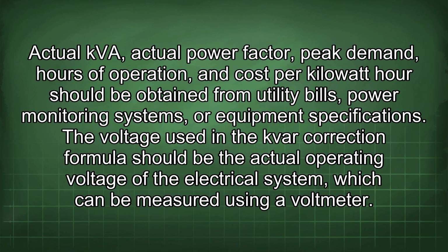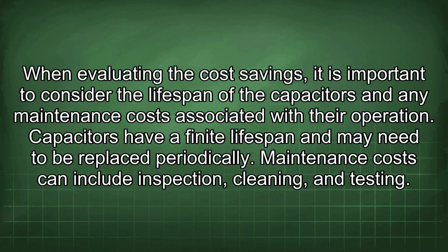The voltage used in the kvar correction formula should be the actual operating voltage of the electrical system, which can be measured using a voltmeter. When evaluating the cost savings, it is important to consider the lifespan of the capacitors and any maintenance costs associated with their operation.